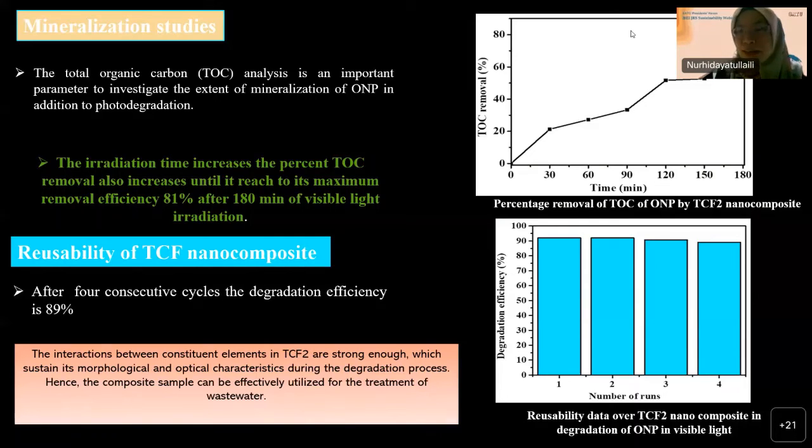To answer the first question, I think they have three questions here. The first one: how we can implement this into our real water treatment or the current water treatments. This system can be standalone treatment, or it can be combined with other treatment. For example, we can combine it with filtration or nanofiltration to remove the suspended solids first, and then it continues with the photocatalytic activities for the aqueous water solutions.